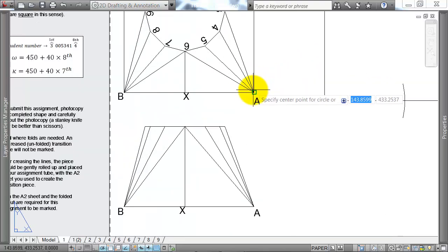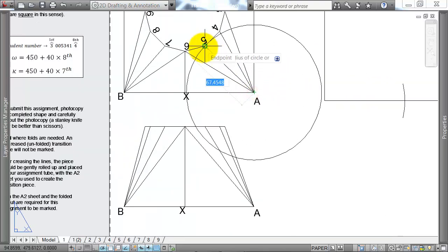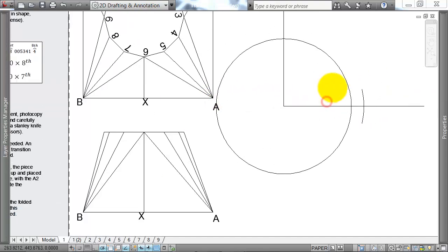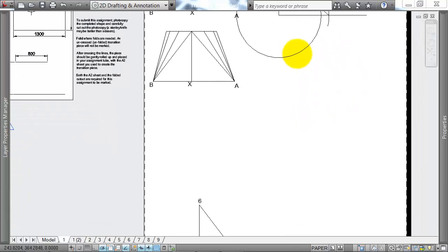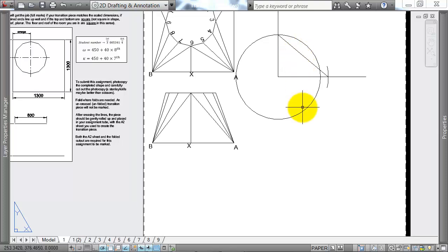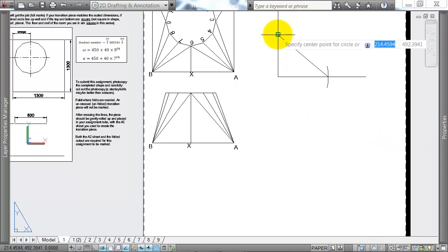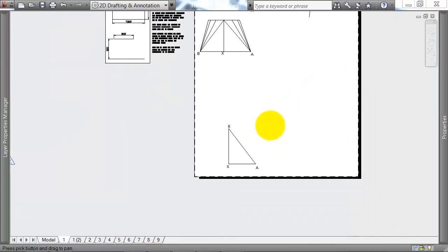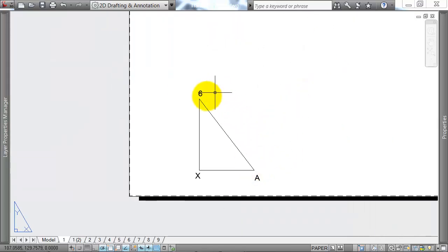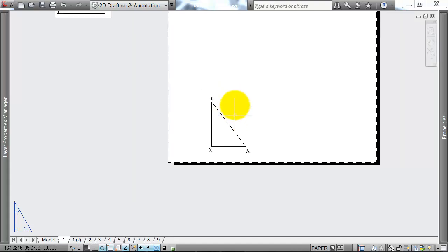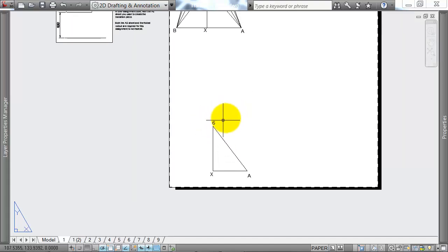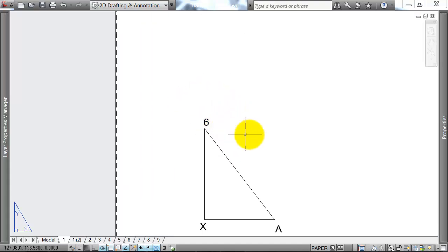So now all I need to do is count the x and y value of line A5, if I want to find this one next. And from here to here, that is the true length of line A5. Now again, this is where it starts to pay to have a good compass. I need to find the point between A5 and 6,5, but it's going to be difficult to locate that in terms of any true math arrangements.